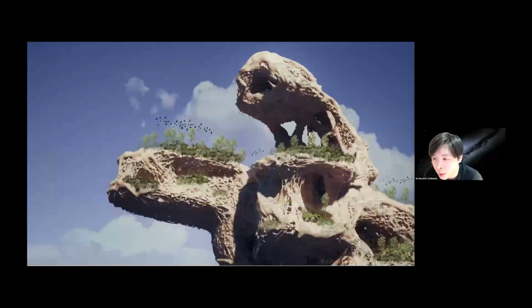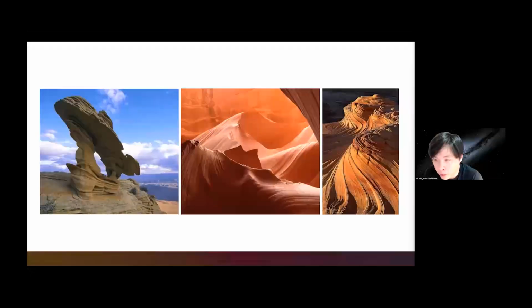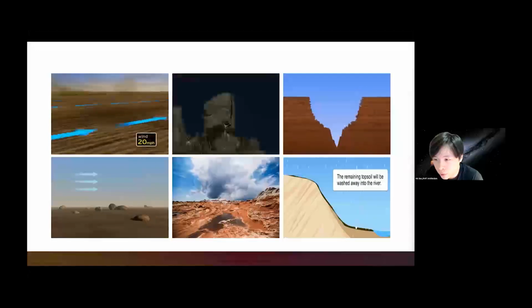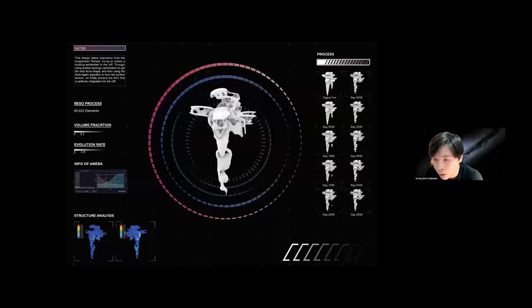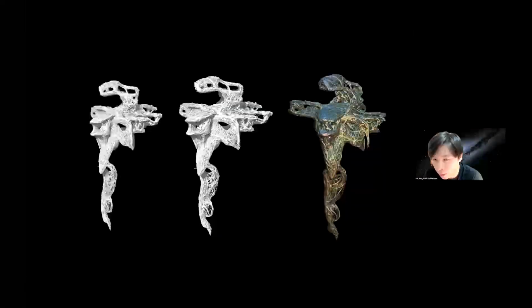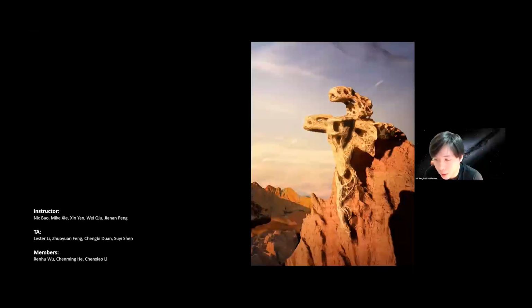And another group of students combined the CFD method with the BESO method. They analyzed the wind loads from an area, gathered data information from nature, and applied the wind load on this interesting geometry, which they called Tempo. They applied the multi-agent systems, which I also mentioned at MIT, integrating multi-agent systems with the topology optimization methods to create this intricate Tempo structure and Tempo buildings. And the final design is touching on the mountain, which is like an icon of some country area.